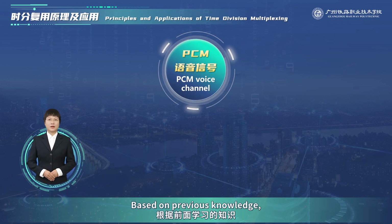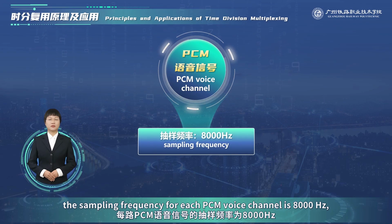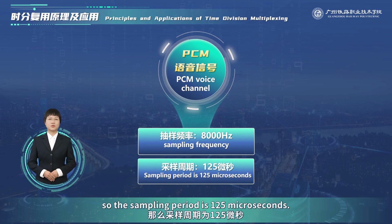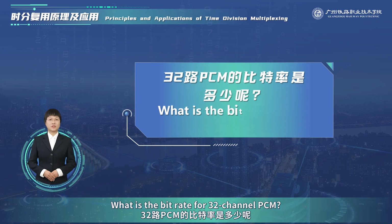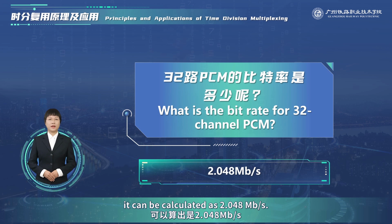Based on previous knowledge, the sampling frequency for each PCM voice channel is 8000 Hz, so the sampling period is 125 microseconds. This is also the frame time or frame period. What is the bit rate for 32-channel PCM? According to the earlier formula, it can be calculated as 2.048 Mbit/s.